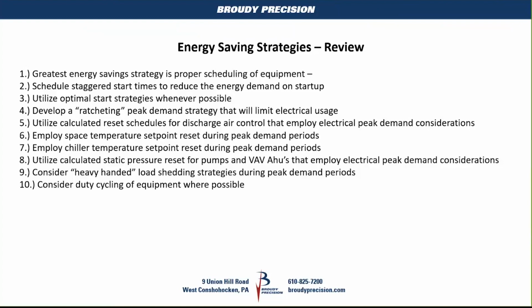There are opportunities that you could capture through the building automation system, and it's intended to be shed during high peak demand situations. And those are what I consider heavy-handed load shedding strategies. And then one of these other heavy-handed strategies is something called duty cycling.